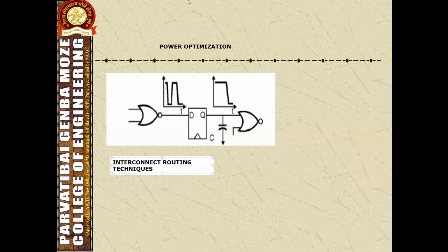Up till now we discussed the flow of the system on a chip. Now we will study the chip level layout and the circuit design. The basic objectives of the design are area, delay and power. Floor planning is called the chip level layout design. The floor planning is divided into three phases: block placement, global routing, and detailed routing.